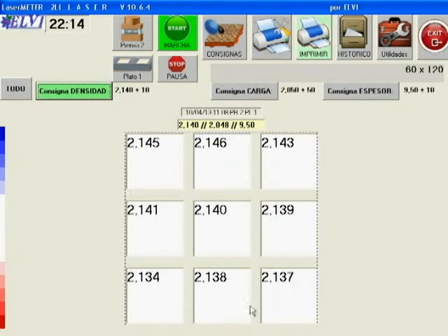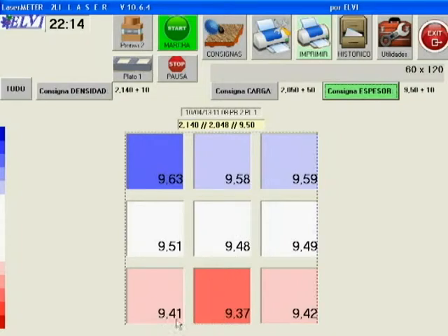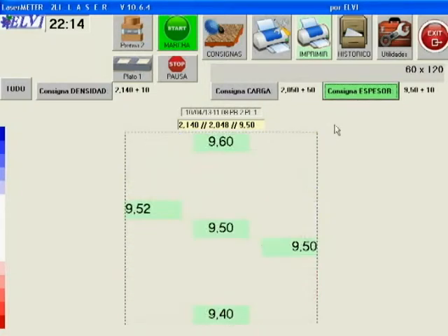In a conventional equipment, we would only have the value of densities, which says to us that everything is okay. Because the bit has been pressed by isostatic punches, and the oil distributes the pressure, equalizing the densities. This equalization carries a variation in the thicknesses, which is minimized if plates of constant rib, also called grid, are used. In this case, scarcely 2/10 of difference is appreciated between the low and top rows, since the variation of thickness is concentrated in the face of the rib, between the supports.